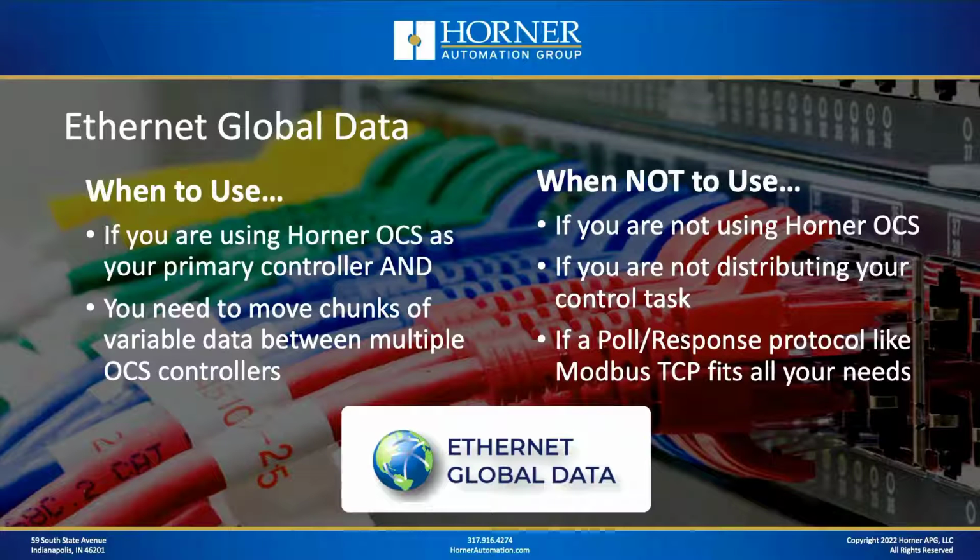If you're not a Horner user, if you're not breaking up your control task into multiple controllers, or if a poll-response protocol like Modbus TCP fits all your needs, then you wouldn't really need to use Ethernet Global Data.